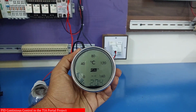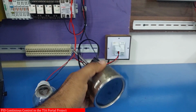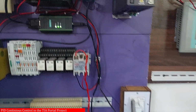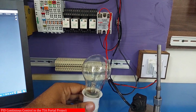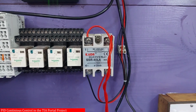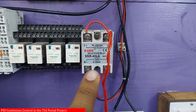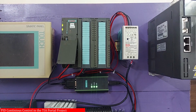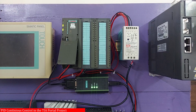We have connected a temperature transmitter with a 4 to 20 milliamp output signal at channel 0 of the S7-300 PLC. And next we have a bulb which is operated by the SSR relay. This SSR relay has a 4 to 20 milliamp input. This SSR is controlled by the analog output of the PLC channel 0 with a 4 to 20 milliamp signal.